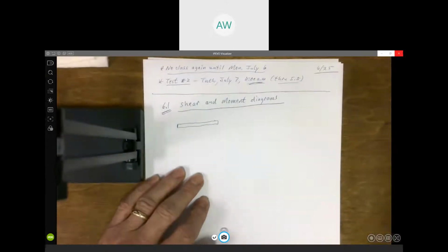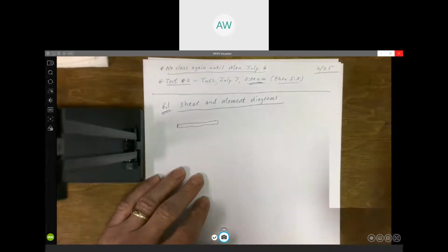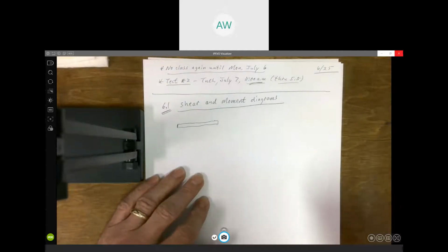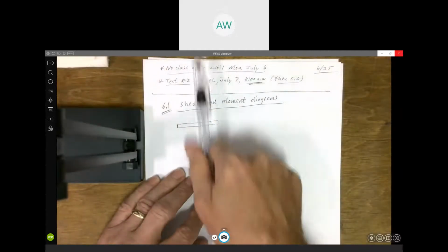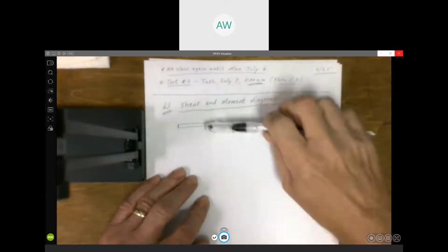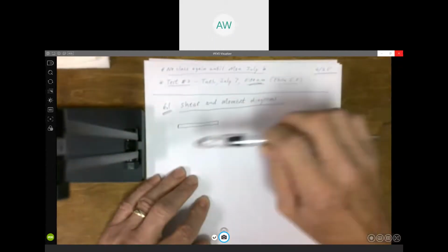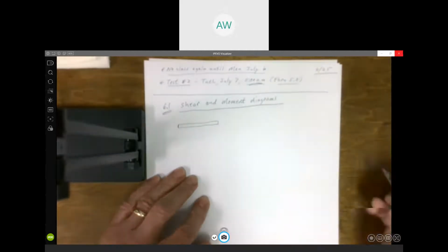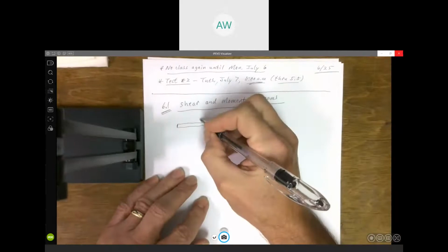also remember at this point we're assuming we don't have any axial loads on this beam. We'll just have maybe a concentrated moment applied, or we can have transverse forces perpendicular to the beam, but nothing pulling the beam in tension or pushing it in compression. And we talked about how we had done this before, right?